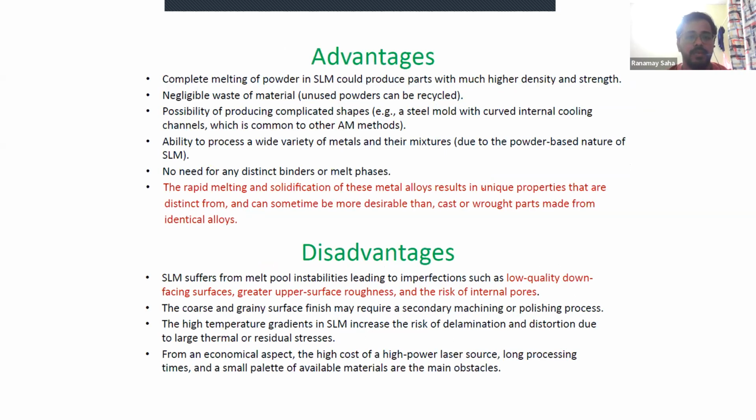Given that, we have the advantages and disadvantages of the SLM process too. So complete melting of powder in SLM means that you have higher strength and density of the product. Okay, negligible waste of material because the unused powders can also be recycled.